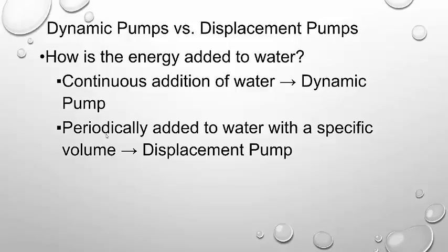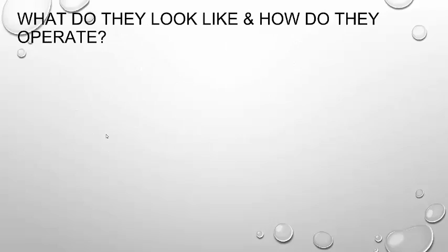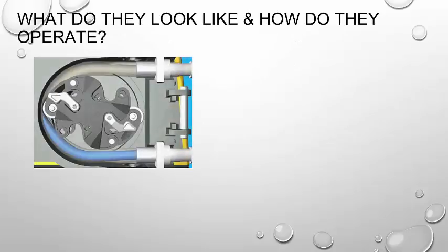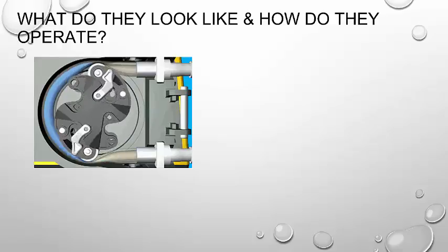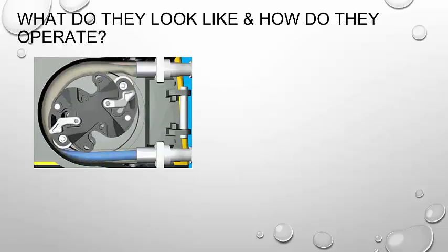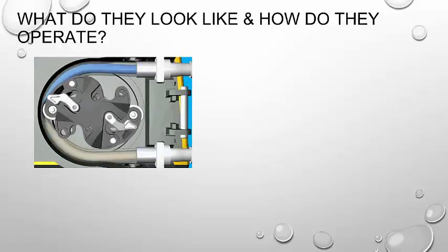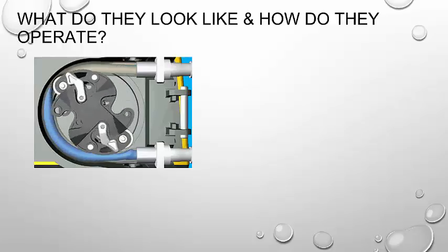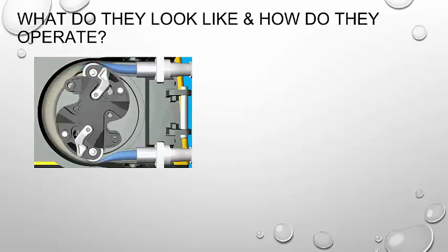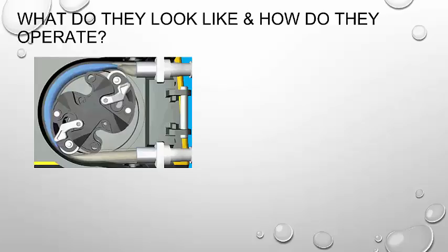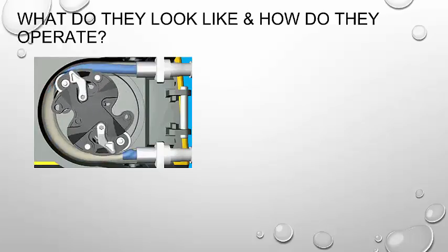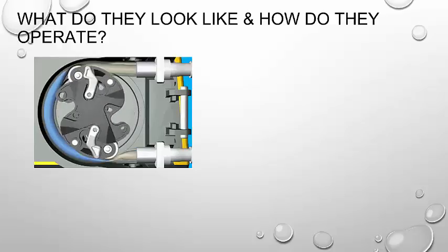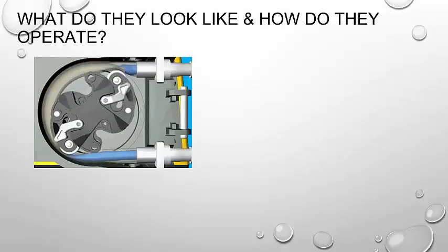If you're like me, you're a very visual individual, and so I like pictures. Alright, so in your head, ask yourself, what is this? Is this a displacement pump, or is this a dynamic pump? Okay, so look at the energy transfer. Is it happening continuously to a continuous stream of water? If it is, it's going to be a dynamic pump.